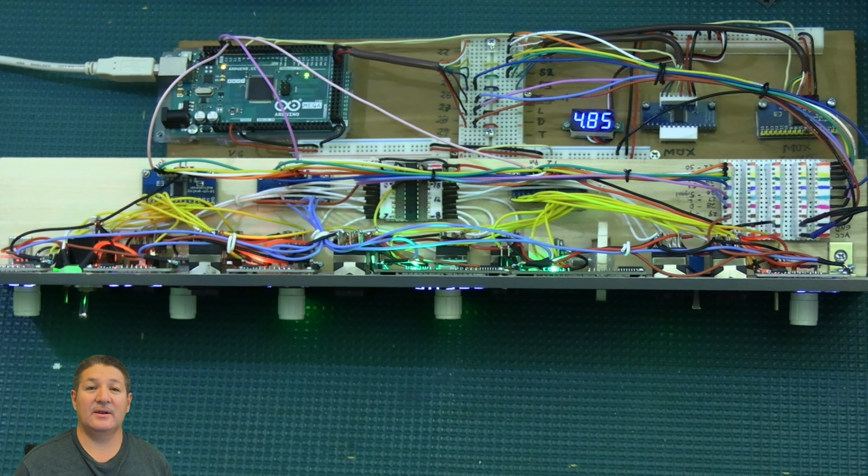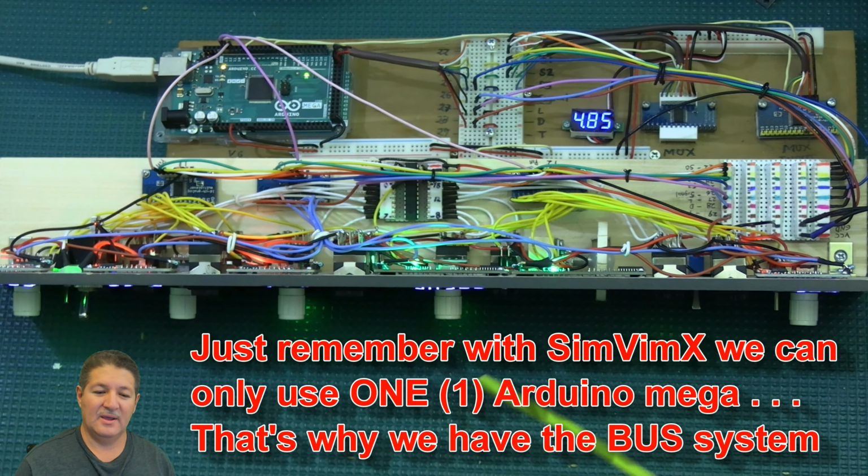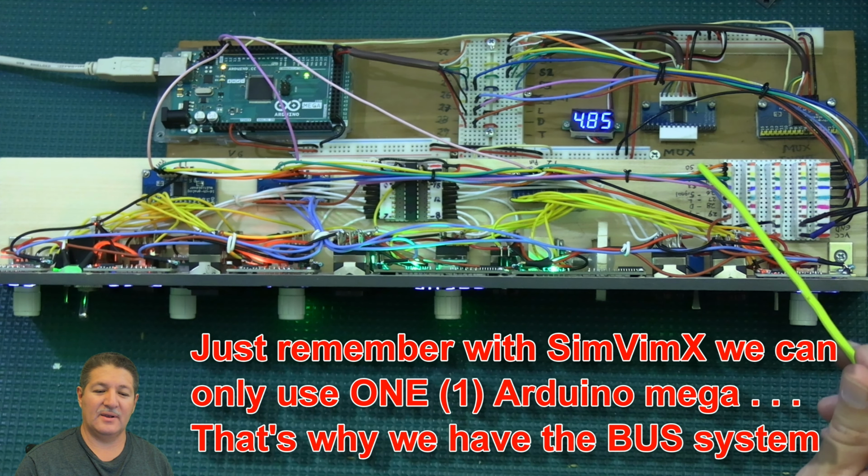There is another way where you can make it an all-in-one solution where all you would need to connect to it is the USB cable for the Mega, and also the power supply to provide the power for the LEDs and the 7-segment displays. So if that were the case, instead of putting a data distribution hub like the one I have over here on the right side, all you would do is put one of those mini Megas, which are probably a lot smaller than these right here. I don't have one right now, so I don't know exactly how big they are, but you could put that one in here and just connect all the data bus wires and the address bus wires directly to the Arduino.